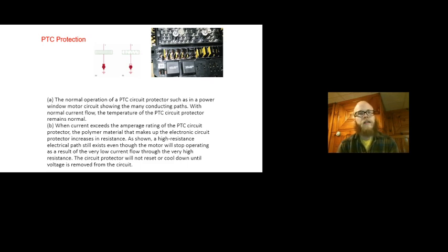As the temperature of the coolant goes up, the resistance of the temperature sensor actually goes down, and the computer sees this voltage drop change that happens across that sensor, and then looks into its little programming library to figure out what 4.3 volts means versus 6 volts.